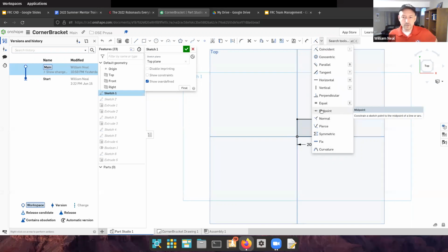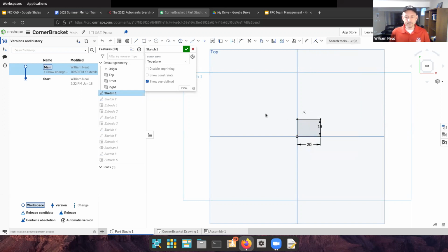What you want to do with a drawing is to specify it exactly as it should be, so there's no way to misinterpret or double interpret the geometry that you have specified. So you want to constrain it just enough, but not too much. You don't want to over constrain it so you get contradictions. These two lines, for example, cannot be parallel, and this one at a different angle than this one. That would be a contradiction.